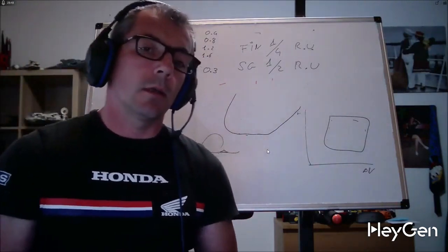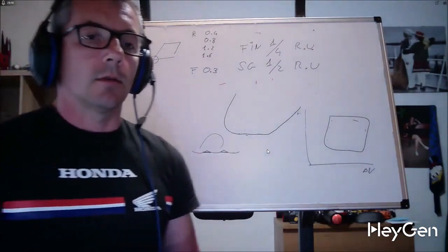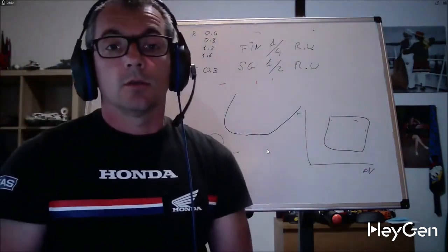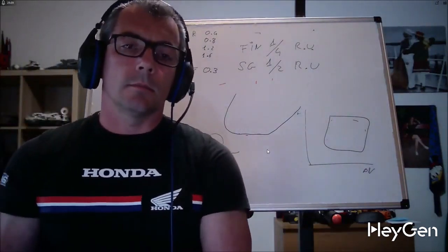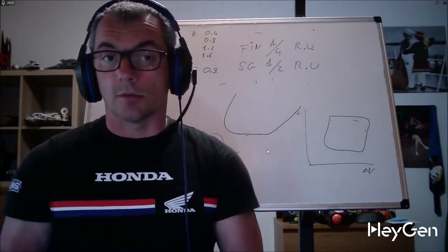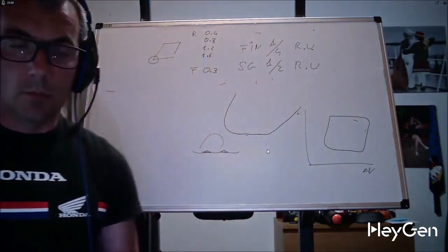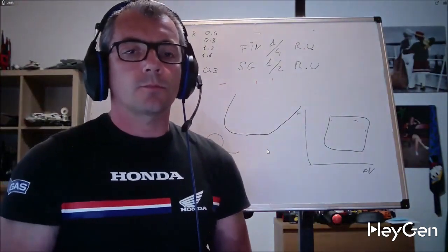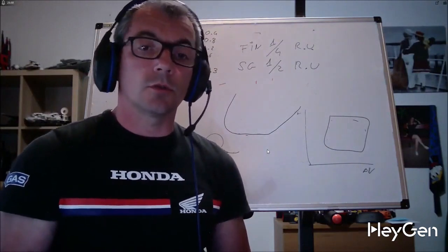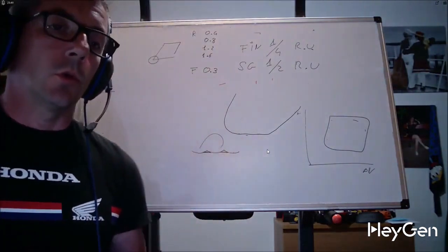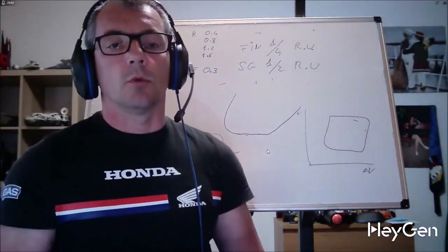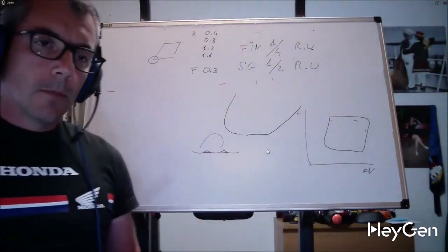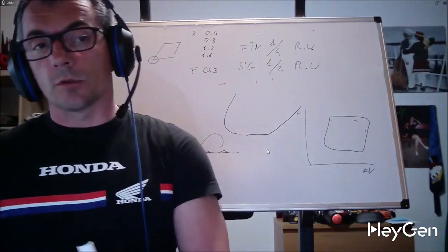If we make a part with a diameter of 30H7, dry at 400 meters per minute with ceramic, it will be hard to leave it there to cool. And after 3 hours we find it at the same height we measured it. Therefore, ceramic is not used for large finishes. I mentioned this to give you an idea. Therefore, it is important, especially if we are working with very tight tolerances, to cool abundantly. If we are working with tolerances of 1 or 2/10, we can also work dry and aim to achieve the maximum tolerance. Okay, but these are things that are separate from a programming course.